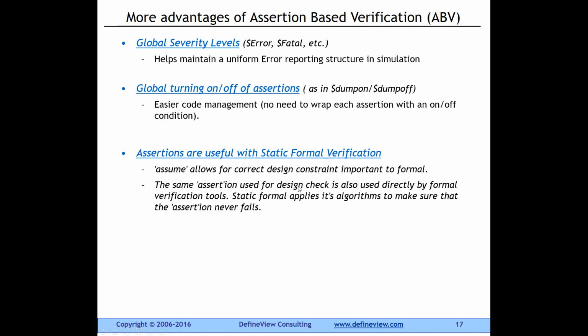Another advantage, and you may or may not be familiar with static formal verification, is that for a given cone of logic, formal verification will apply all possible combinations of the input in both combinatorial as well as temporal domain. This is different from writing your own test bench. It's exhaustive.